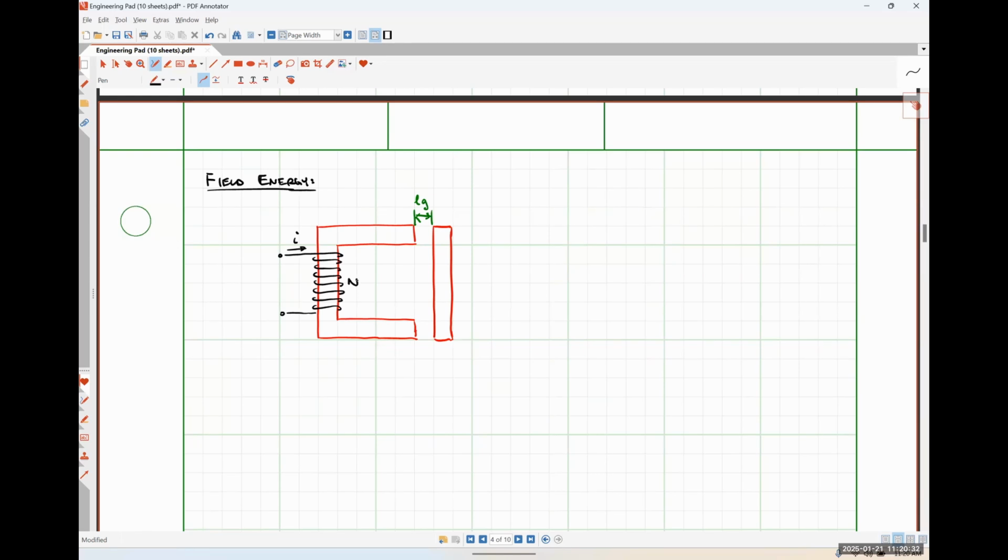So I'm going to also add a little bit of an electrical input system over here on the left, which is simply just going to be some sort of source voltage. For now, let's assume that this is a DC quantity connected in series to some resistance R. Let me just do it as R without the S for right now. And the voltage induced across my coil will be lowercase e.